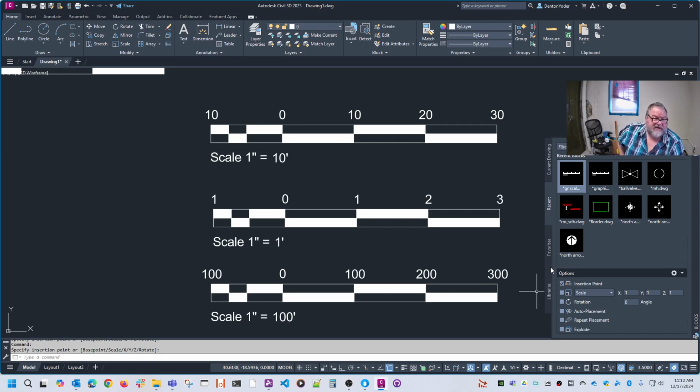We're always going to use these in paper space, which is 1-to-1 scale, so we don't need to ever scale them. Okay, I think I've shown enough about drawing, the W block command, and the insert. I think you're ready for the second blocks video now. Take care. Bye.